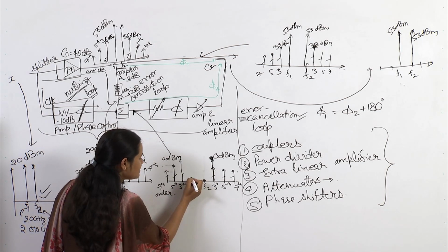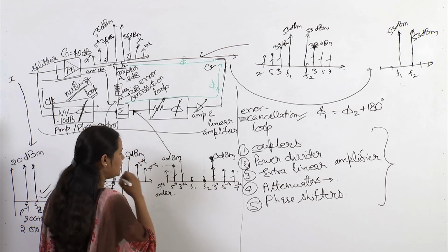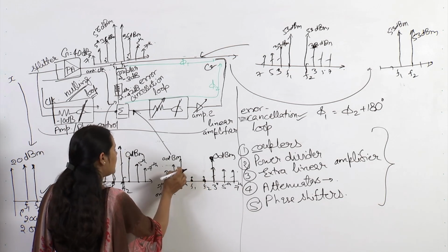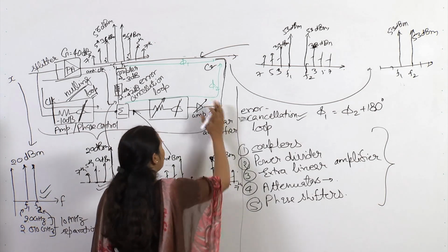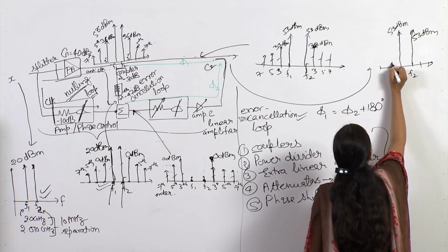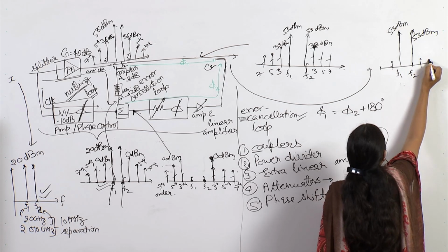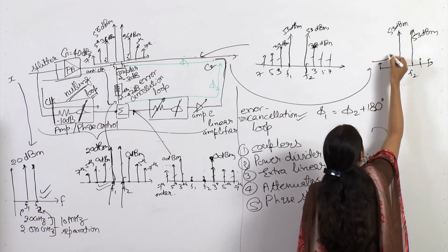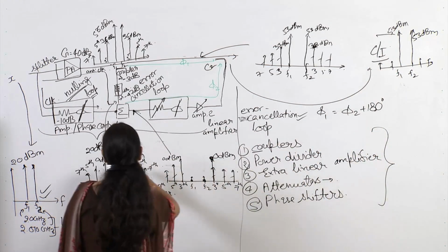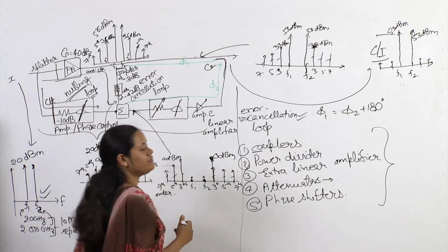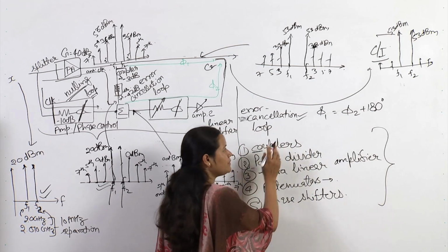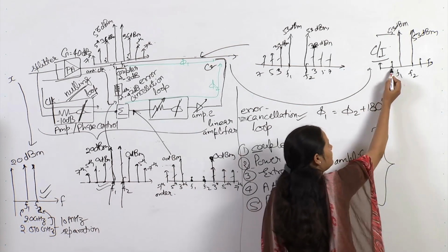What you can see some small signal here, right. So, because of this imperfection, you will see these small signals here, and when this path will go and meet with this path, then in turn you will again see some IMD terms here. It will not be completely cancelled, although C by I ratio might be much higher than the previous one, which when it was almost 20 dBc. Now maybe it will be 50 or 60 dBc depending on how perfect your systems are, but because they are the real system, they might not be perfect, and you can see some IMD terms here.